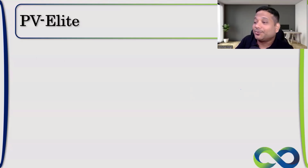Division 1, Division 2, EN 13445, and PD 5500. So these are the codes which normally are referred by PVElite. So PVElite is one software which caters to multiple codes. That is the biggest advantage of PVElite. And it comes with the same license. The basic license which is given, with that all these codes are inbuilt. So that is the biggest advantage.